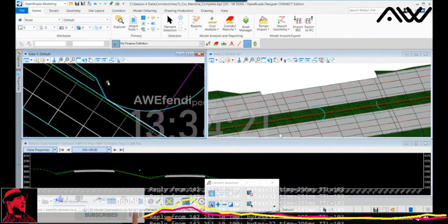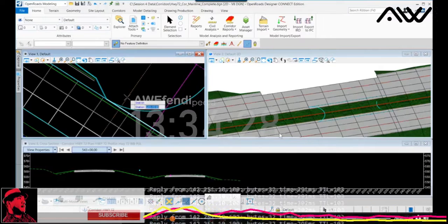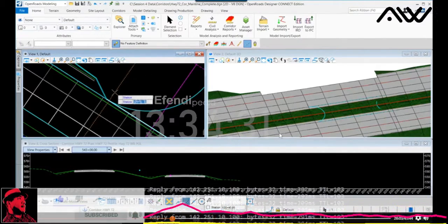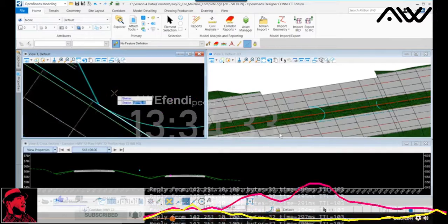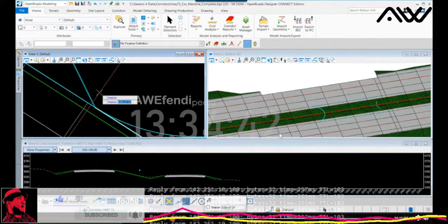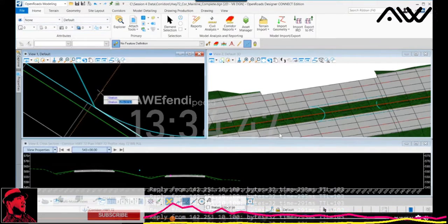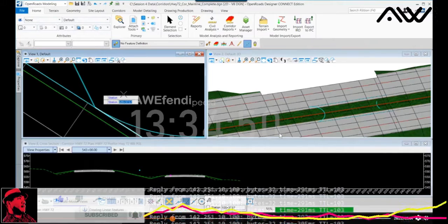I can do that by using key stations. So I'll select the corridor once more and select the key station button. Now I don't want this to occur past where the intersection begins. I want this to occur slightly before. You could mark this off as a hundredth before the station if you want. It's not super specific, but you want it to be slightly before this point. I want one final template drop before I get to that point, and you'll see how this is going to tie the model together as we go through this. So I'll add in that key station.